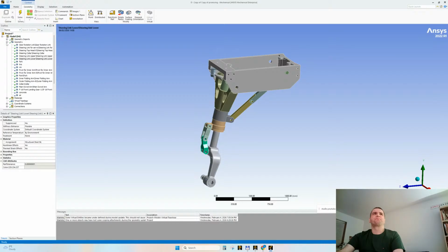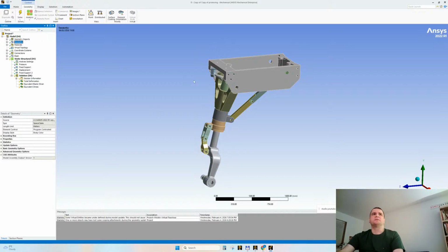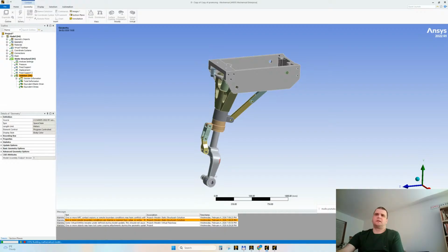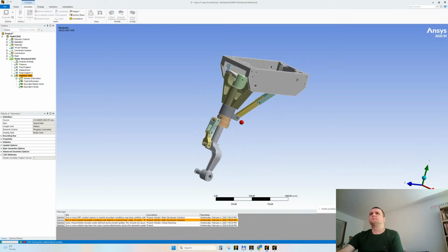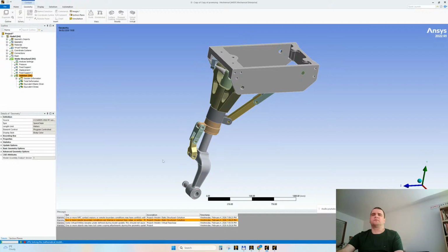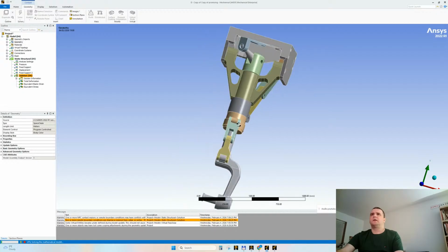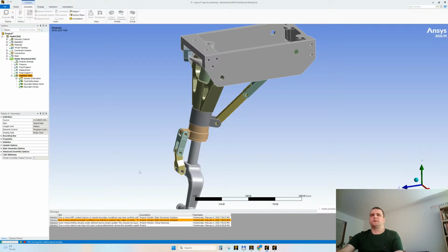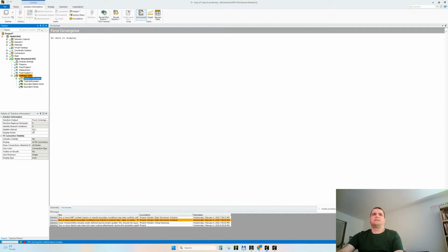Yeah. So I fixed here and I am displacing here. Let's solve. Then we can see where the problem is, because usually the nonlinear contacts give problems. Maybe also having the hyperelastic material, it gives problems. Usually such a scenario is to be debated and researched and tested for days and weeks, and doing it in 1, 2, 3 hours live, it's a big stretch.